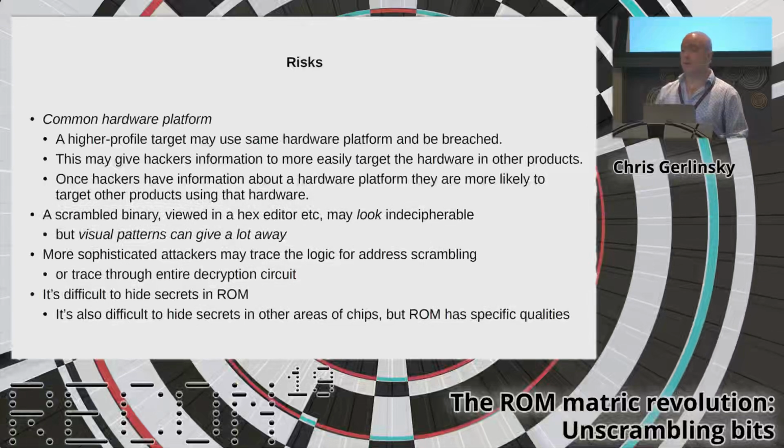So, some risks with trying to keep ROM data secure or secret. The first one is the common hardware platform. If you're using the same chip as another product that is going to get hacked, then hackers are going to attack somebody else's product and use that information to hack yours. Once they understand the underlying hardware platform, anything using that same hardware platform becomes low-hanging fruit, and it's very easy to extract. So even if you weren't a very interesting target before, you might become a more interesting target just because the hackers already have knowledge of the hardware.